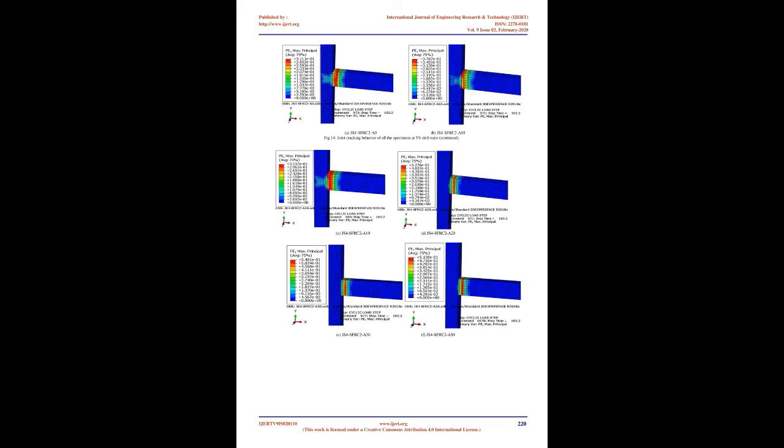The specimens JS4-SFRC2A05, JS4-SFRC2A10, JS4-SFRC2A20, JS4-SFRC2A30, JS4-SFRC2A50, JS4-SFRC2A70, and JS4-SFRC2A75 exhibited their average maximum loads of 103.59, 103.95, 104.79, 104.23, 104.38, 104.35 and 104.74 kN, respectively.